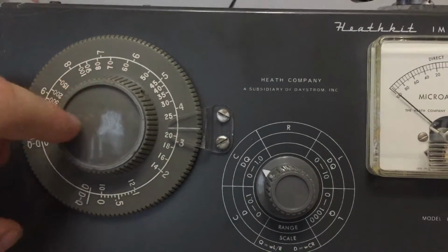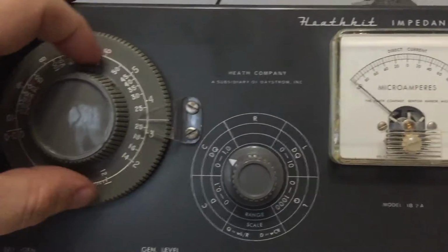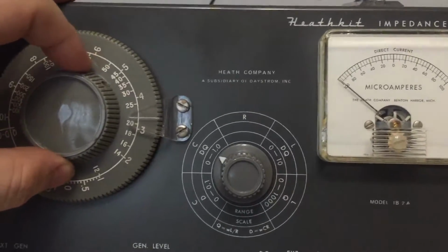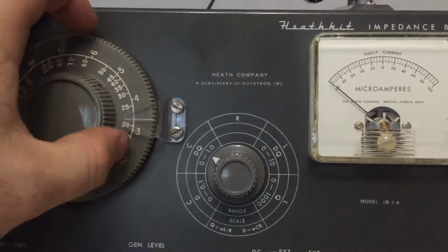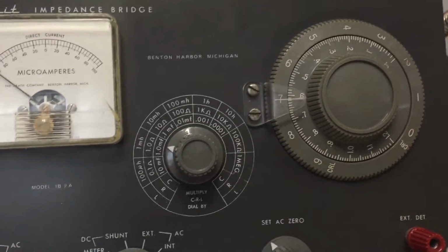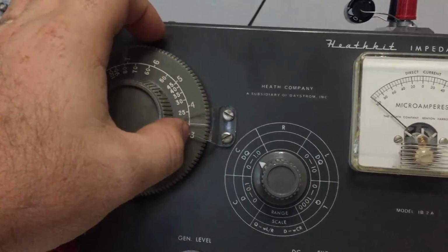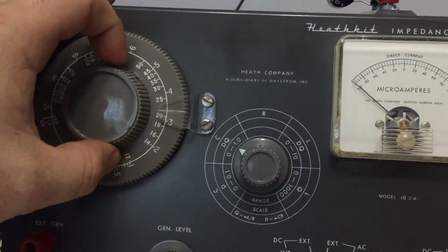And obviously, if I start doing some computations with this Q to get the ESR from the dissipation factor, we can see how close I am with those values. The problem is, again, like I said, frequency and capacitance, and obviously pi being a constant, this is always going to be an issue. So we're going to have to work within a tolerance. You're not going to have exact measurement in ohms. We're going to be off.